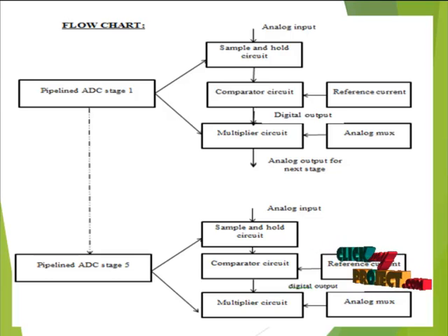We get the 11-bit analog input and give it to the sample and hold circuit. In the process, a transmission gate based design acts as the sample and hold circuit. The gate is made up of a parallel connection of an NMOS and a PMOS. The sample and hold is used to convert the continuous signal into a discrete signal, and then the circuit holds the value at a constant level for a specified minimum period of time.